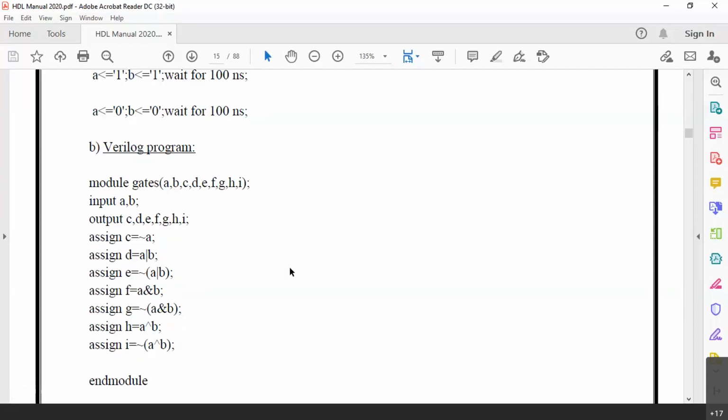For example, if at all we write a code here, for which there is no counterpart in the registers in the software's library, then the hardware does not exist there. That is why I told you, non-synthesizable code is useless for us. If any code does not yield a circuit diagram, it is useless for us, because ultimately we want hardware out of the code. So that is why it is called RTL. Now remember my statement, all RTL is HDL. All HDL need not be RTL.